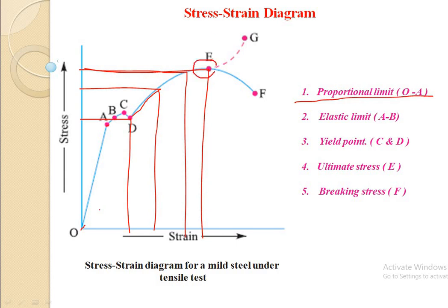Now this is the ultimate stress, the maximum resistance offered by the material to its breaking. It is actually the design criterion for brittle materials. It breaks at sigma ut, that is ultimate, and sigma yt is the yielding, because yielding occurs in ductile materials. But without any yielding in the case of brittle materials, the material breaks at the ultimate value of stress.